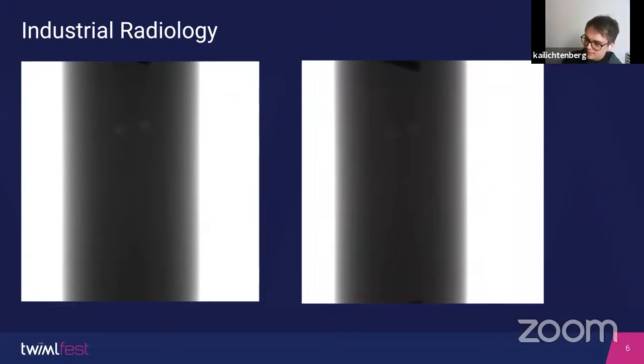But the thing is that computer tomography is often very slow for making images of a significant number of parts during production. And AI can help here. When you do faster imaging with a CT machine, you get worse pictures, with a lower signal-to-noise ratio. And a CT image consists of many individual pictures, as you maybe know, which are then assembled into a three-dimensional representation of the part, or of the component.